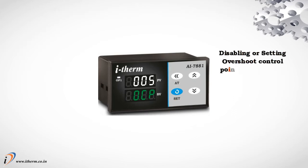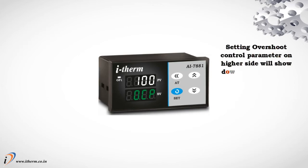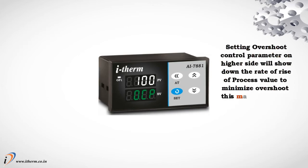Disabling or setting the overshoot control point parameter on the lower side will increase the rate of rise of process value, which may cause overshoot. Setting the overshoot control parameter on the higher side will slow down the rate of rise of process value to minimize overshoot. This may cause delay to reach the set point.